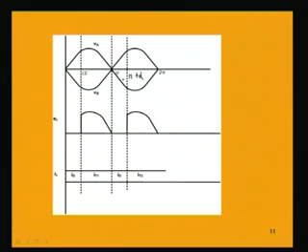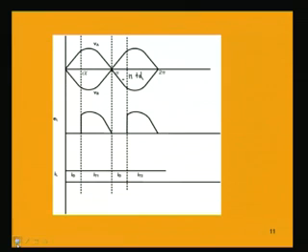When the diode is conducting, the diode voltage is 0. So, this is typically the output voltage waveform for a full wave rectifier using a center tap transformer and flywheel diode. So, here we have seen that the rectification using this thyristor will have an output voltage waveform across the load with no negative portion.